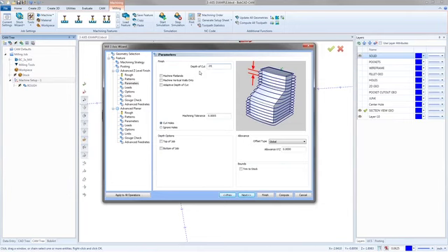So I'll go 50 thousandths over 20 thousandths. Less toolpath, less time to calculate. The other trick to getting a toolpath to calculate a bit quicker is to change that machining tolerance. But you've got to be careful with this one because it'll change not just the quality. Well, it changes everything. The speed of the toolpath, yeah, it'll calculate a lot faster. But the quality of the toolpath can drop as well.